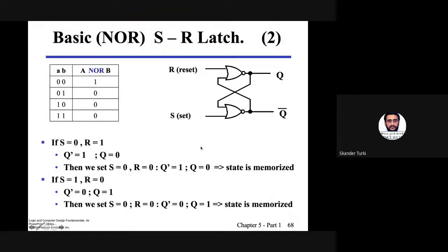So you have to select the pen. If we set here 1, here 0, 1 will give us 0 here. So 0 and 0 will give us 1 here. And then the 1 here, when it loops back, will not change the 0. We will not have a continuous change in the state of the system. The system will be stable like this, will stay like this, and will not change anymore.